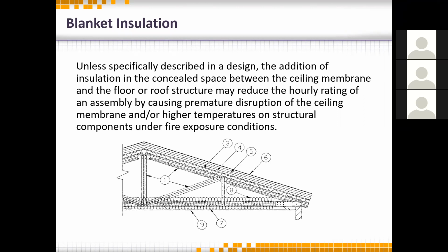So with these specific designs, we can add insulation if it wasn't tested, but we have to add an additional layer of drywall. Flipping this to partitions that were tested without insulation, you can add insulation to them all day long and you don't have to do anything different. Okay, so the wall's different.